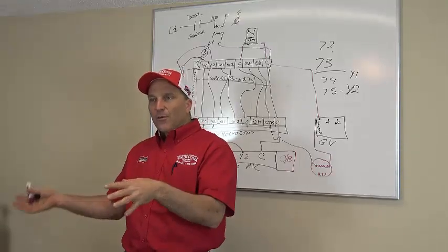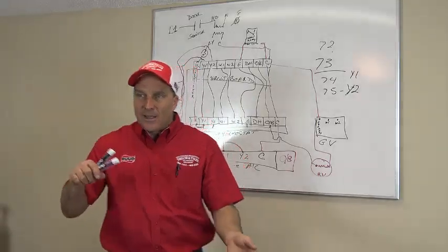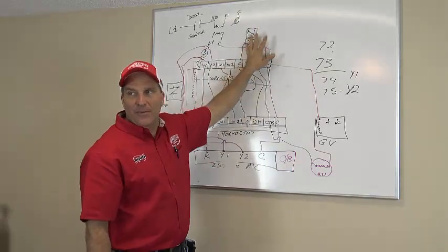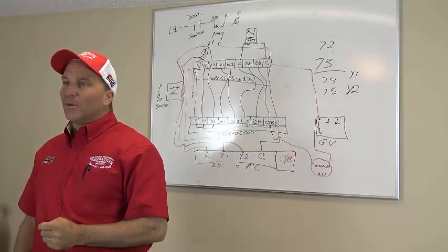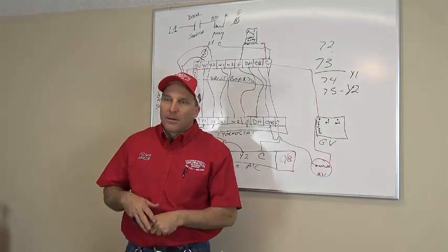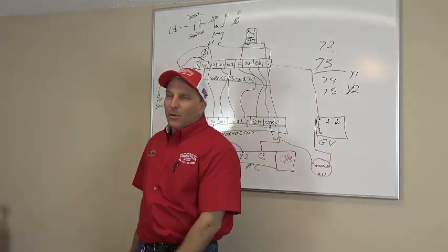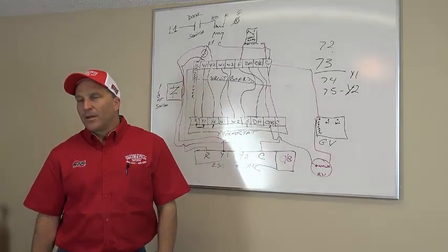So then once it defrosts, it goes back into the heating mode. Then the heat goes back around on the inside and starts heating up the inside, then the fan can come back on. Do you ever even know it did that? No. You have no clue, because the inside's turned off, so you don't even know it's doing anything outside. Now my fuse blew to my outdoor unit. I no longer have any heat pump, right? Fuse blew. Where am I going to get heat now?